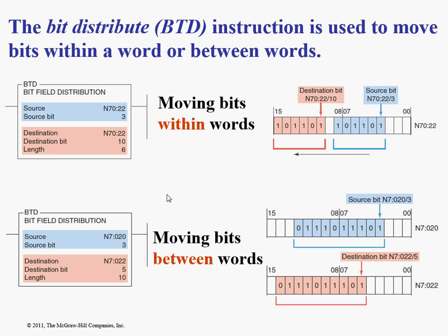It just put it all in one 32-bit word, so I ended up with two numbers in one slot. I had to take the last 16 bits of that number, yank it out and move it around manually, so I got the correct barcode into the new 32-bit PLC. I had to use a BTD instruction to pull that off.